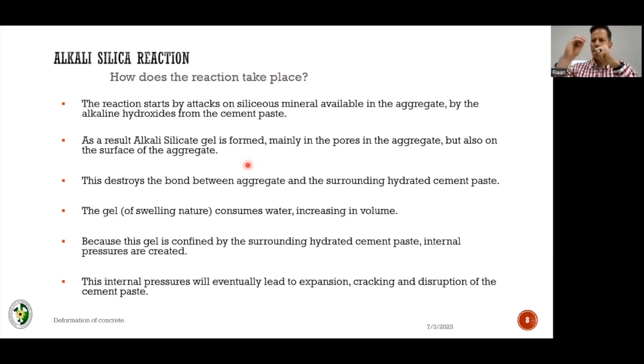This is where your cement particle was sitting in space with a solution of water, and it's now reacting, and it was growing gel particles, and it's touching your aggregate. It's not gluing itself to the aggregate, it's literally touching. And if you surround this aggregate particle, you end up with a situation where this aggregate particle now becomes locked in space, as does the one next to it, and the little sand particle, and a coarser sand particle, even a finer particle, and cement particles, and GGBS particles.